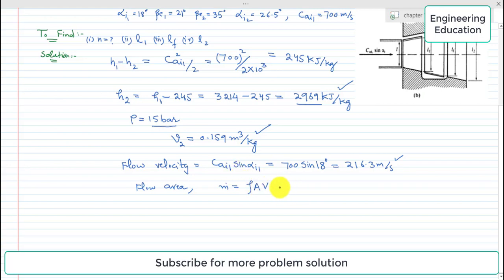So replacing rho by specific volume, we can write m dot equals A V by specific volume, or we are interested to find the flow area. So for this we can write: A is equal to m dot into specific volume divided by velocity, which is the flow velocity. This is the flow velocity represented by V.